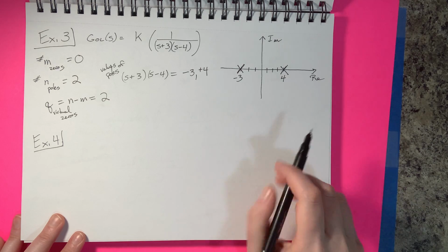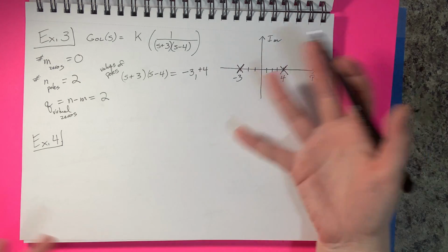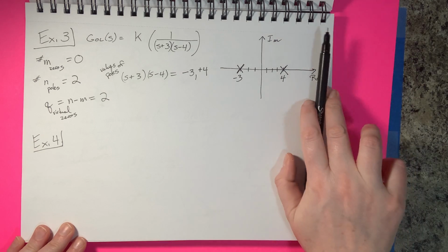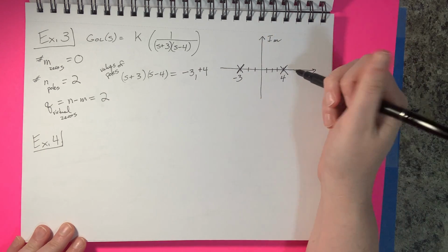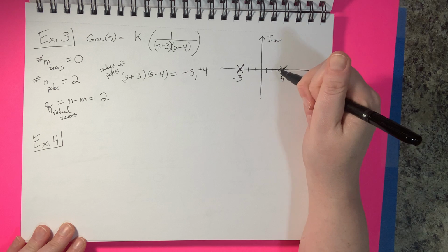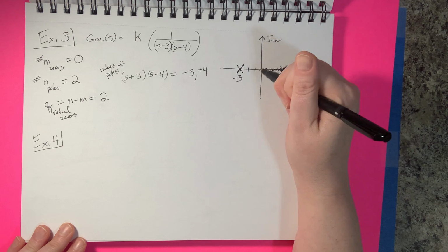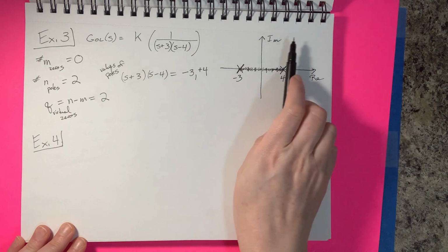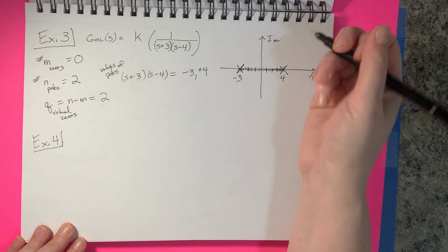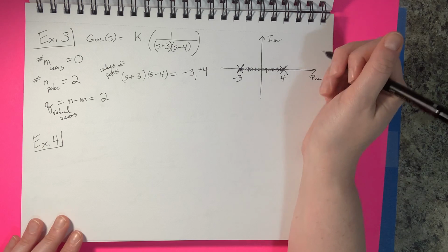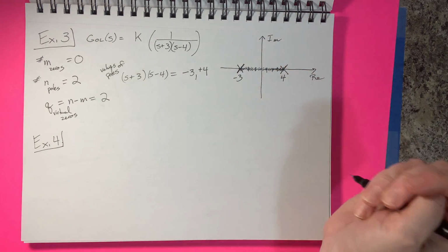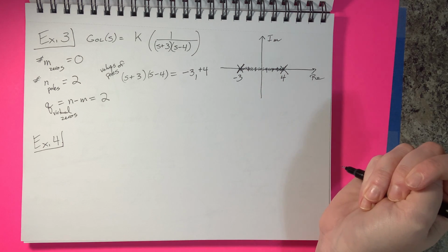So let's apply the real axis rule again. This rule is very handy, told you so. As you move your pen across here, this is going to be odd. There's 1. And then once we pass the second pole, it's even again. As we move the pen, we look rightward. So what happens in this case, we can apply our collision rule. They're on the real axis, so we're using the collision rule, not the complement to the collision rule.